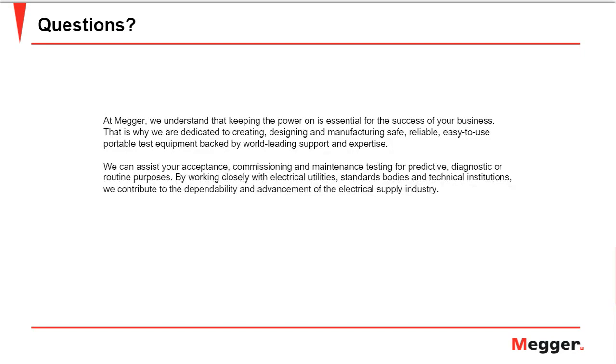And I say that knowing that a lot of times reverse power elements are used as polarizing elements for overcurrent protection, thus turning that overcurrent protection into a directional protection, which is one way of achieving directionality. Okay?